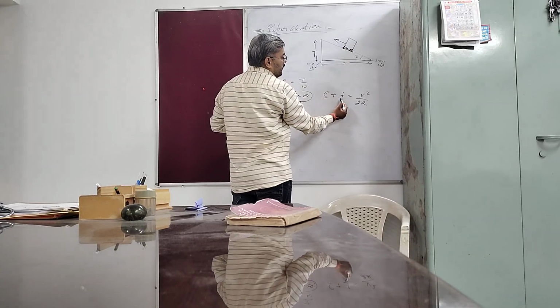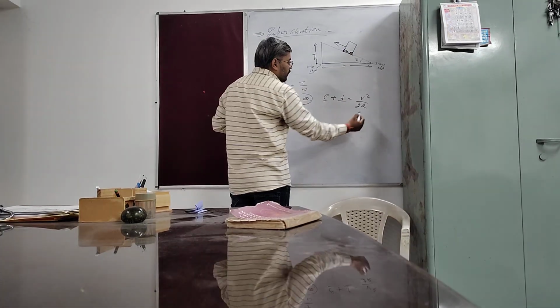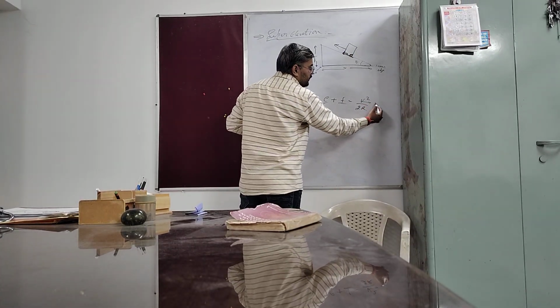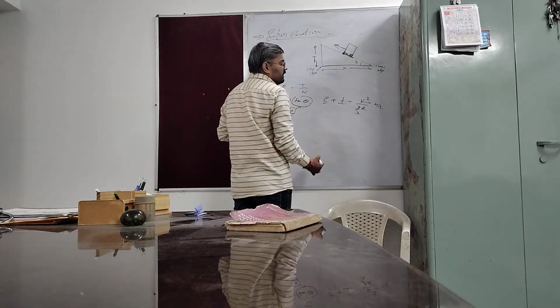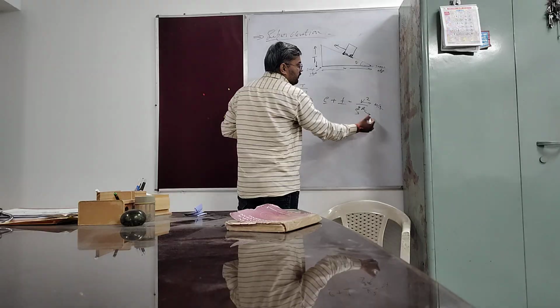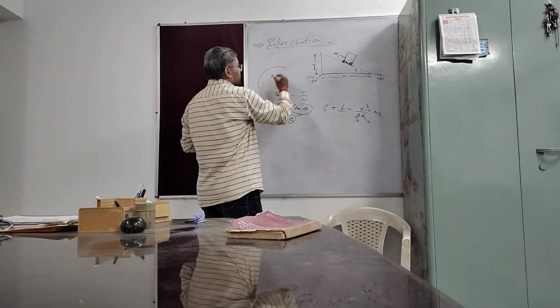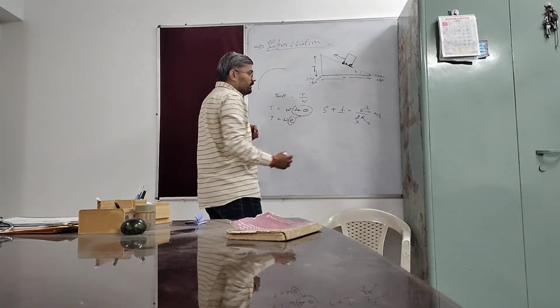That friction is called the lateral coefficient of friction. And here V is the speed of the vehicle in meters per second, G is the acceleration due to gravity, and R is the radius of the curved surface on which we implement the super elevation.